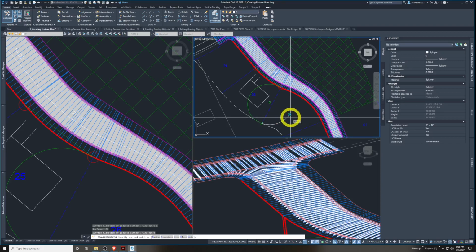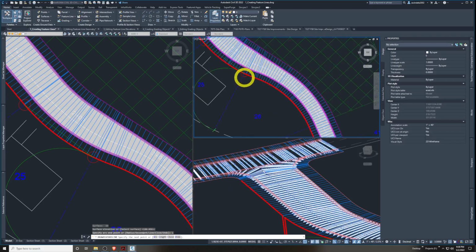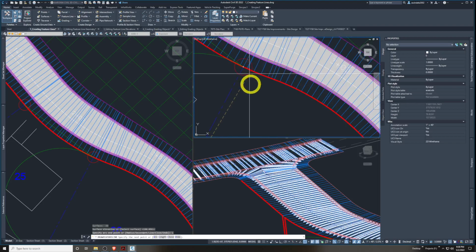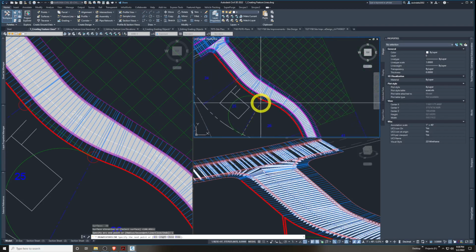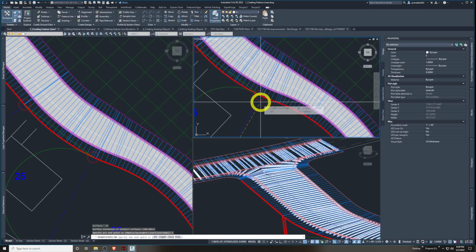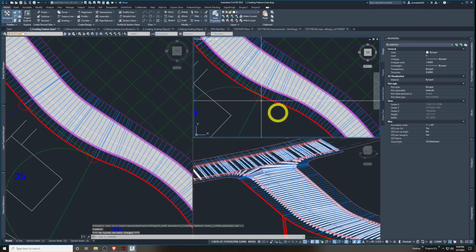So now we can continue on with arcs, or we can go back in this nature, whichever direction we want, or we can go back to line, which we're going to do. And let me select the next point. And it just says to pick the center point, which I can turn off nearest. That's kind of a bugger one. And we can get the center point, hover around this circle to the east corner of lot 25. And I would call this the easternmost corner of lot 25, even though it's kind of in the northeast. Select that, and it accepts.